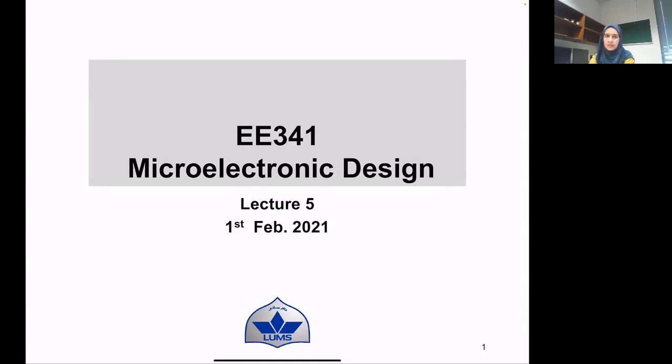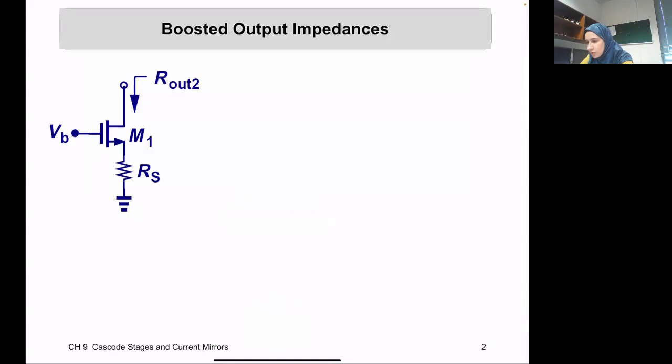Cascoding and the benefit of doing cascode. Cascode, if you remember, looks like we basically have a source impedance at the amplifier. So the source is not grounded, but the source has an impedance that is either RS or any impedance. And we like to have this impedance to be large in order to get the larger output impedance that we want to have here.